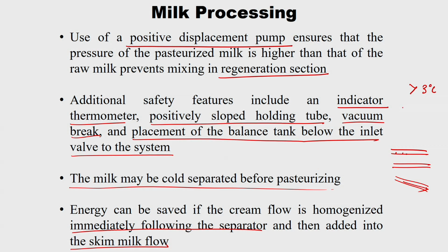For example, batch process ensures 63 degree temperature for almost 30 minutes. So, your head space should be maintained at least 66 degrees centigrade to avoid any temperature difference, and also because it loses the heat, right, because the top layer is at 63, if your air layer is at normal temperature, there may be a delta.